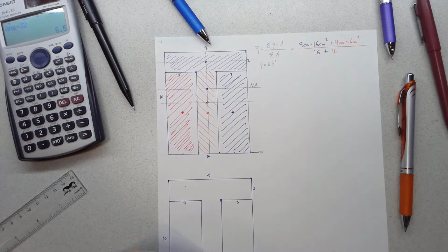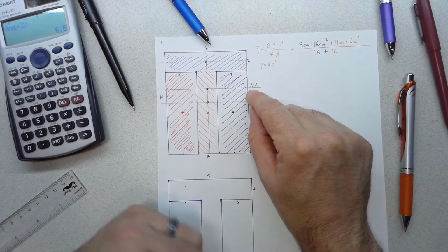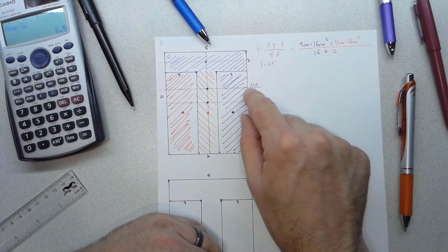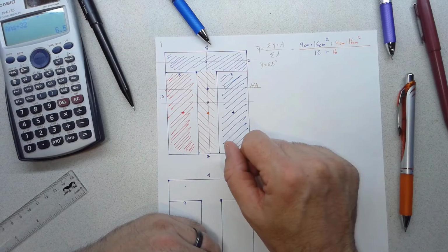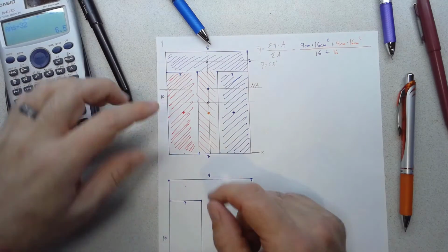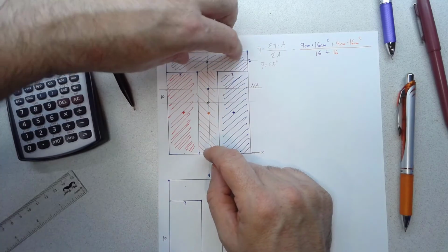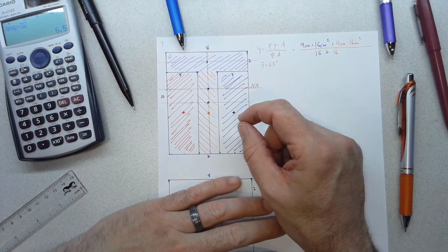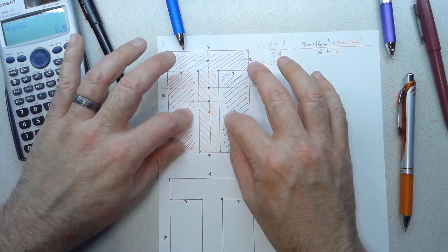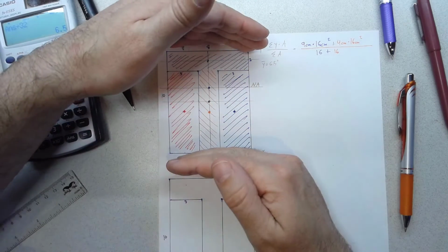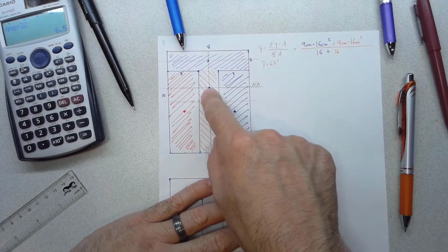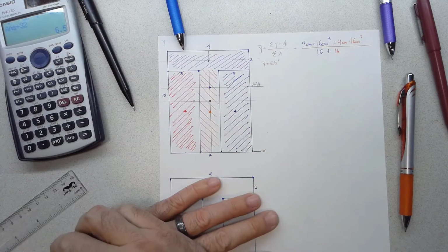Okay, and why I have to find that is because when I'm looking for I for this composite shape, I'm always looking for I about the neutral axis of the shape that's being bent. So in this case, I had to find where that neutral axis was located. And again, I did it by adding up these two component areas. I could have found the centroid by finding the centroid of the big rectangle and then subtracting these two. Again, you can do it either way. You can do it referenced from top or bottom. However you do it, though, you should find that the centroid is 6.5 inches up from the bottom, located on the axis of symmetry.